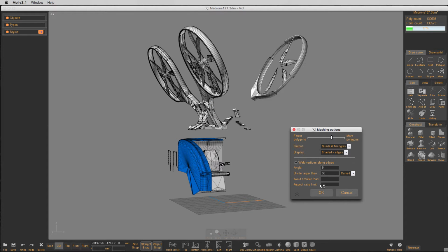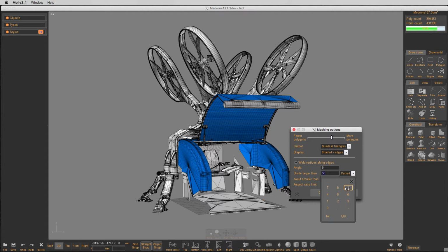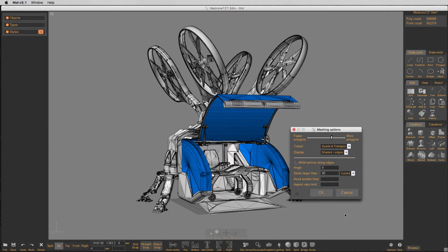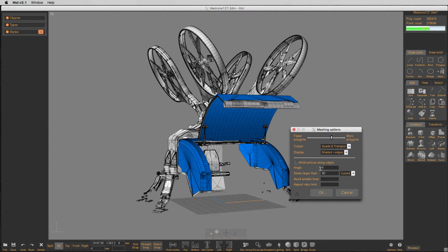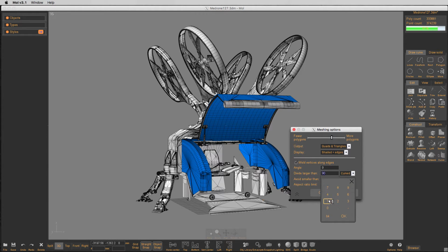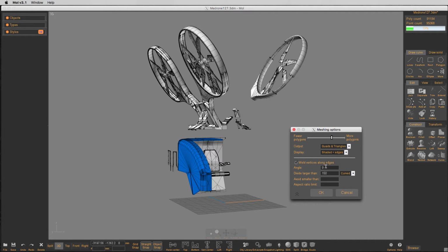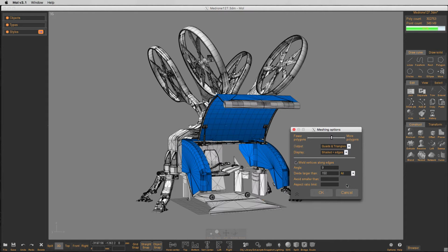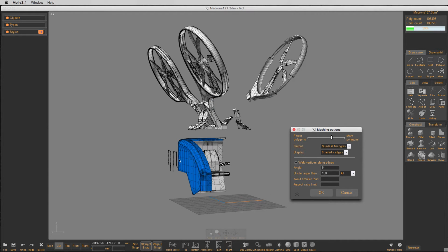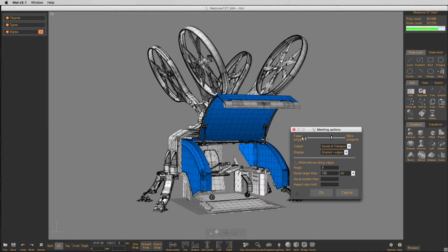And then I want to break those up into, let's do 90. So as I do this, it's continually updating. Let's do 150. So I'm getting kind of a good feel for how big these areas are. And then instead of curved, now watch, I'm going to say all. And now watch, it'll grid all of this out. So now I'm not going to probably get those kind of smoothing errors that I saw